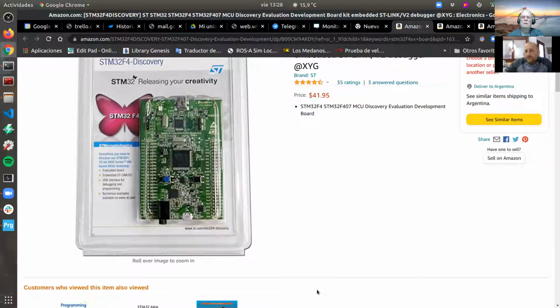So I'm a bit stuck in this, Chef. Once you do figure out how to program the board, back in your IDE, all you have to do is change the pins on that page. I don't think you have to modify the software at all. Whatever device you're going to use, a motor controller, it's got a direction and a PWM. Just figure out which pins on the old board it's hooked up to and hook them up to those pins on the new board. You're just going to have to hook up the wires in the right spot on your board to make it do what the old one was doing.